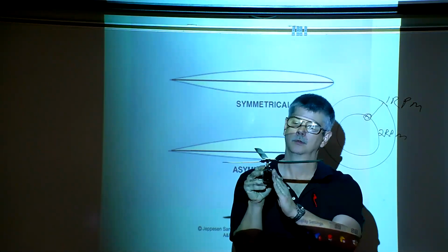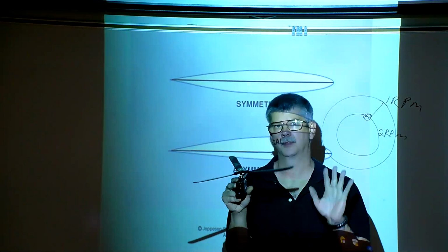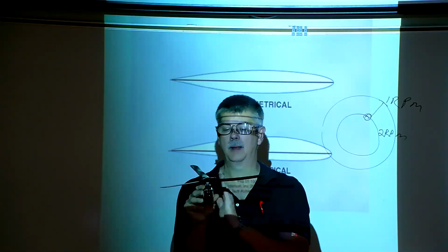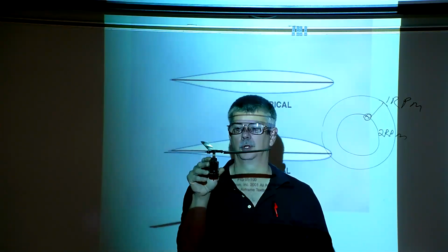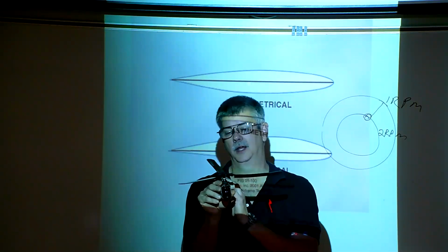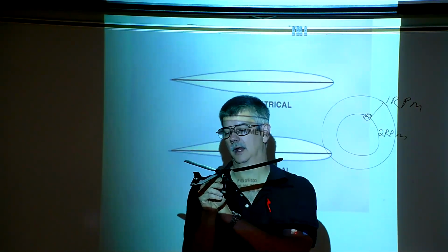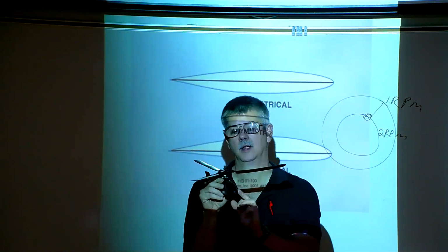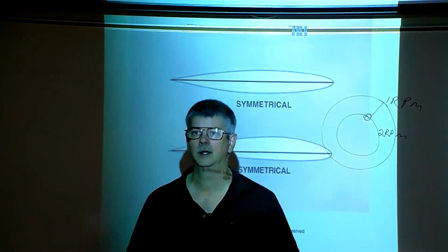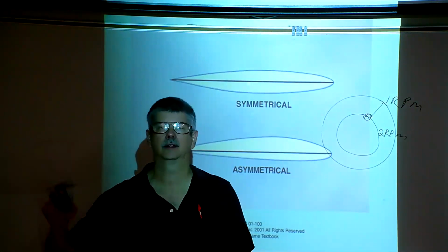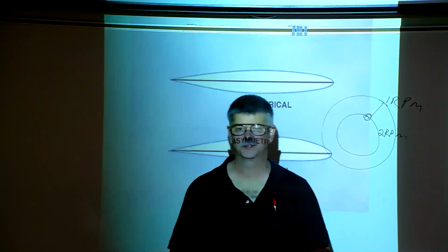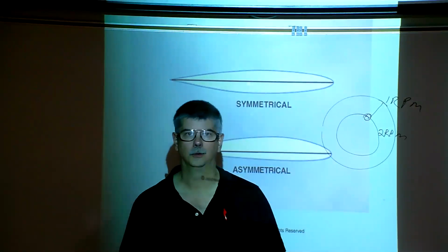It's set up so that when the rudder pedals are neutral, it puts out enough thrust to keep the nose straight. The problem is the tail rotor is pushing the tail to the right, and the torque of the rotor blade is pushing the nose to the right, and thus the helicopter had a tendency to drift to the right. To compensate for that, they could do two things.